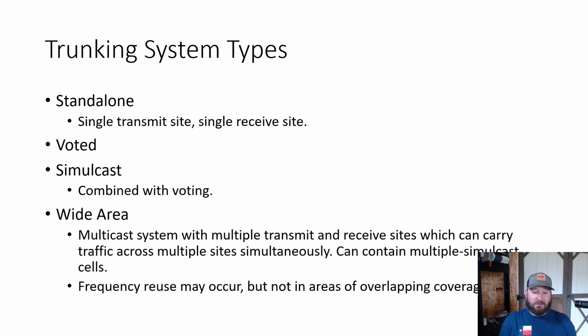That pretty much is a basic quick wrap up of how these basic radio systems work. Trunking can get very advanced, and like I said, you have these massively large systems with 100, 150, sometimes as many as 400 RF sites to cover an entire state. And your trunking systems can be made up of multiple channels, upwards of 30 if we're using a phase 1 system, or a system that does not divide everything into TDMA. But we will discuss that in a later video.